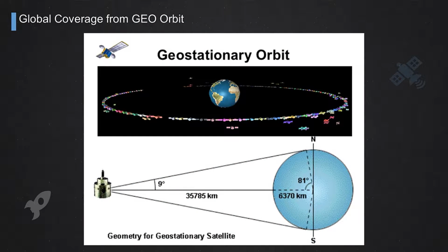So we want to cover as much as possible of the Earth, having our satellite, as we said, at approximately 36,000 kilometers above the Earth's surface. So we see the geometry of the link, if you want. The Earth is seen, almost the full Earth, because you see that it cannot really reach the north and southern pole, but most of the Earth is seen from a geostationary satellite, from the geostationary orbit, under a total angle of approximately 18. As a matter of fact, it's a bit less, 17.5 degrees, okay?